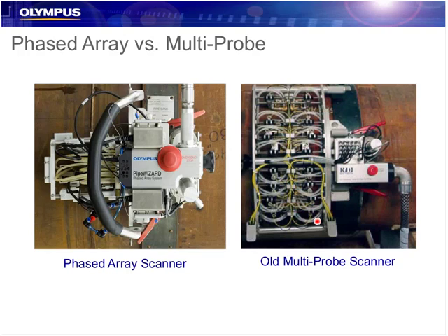We can imagine the trouble with this. Very precise. We have many, many different parts that can move. If one transducer becomes misaligned or if the scanner's dropped, we're basically not getting the full coverage of it. So now with phased array, we're able to replicate all those beams, actually get even more coverage than we could from 30 UT probes, and the mechanic is highly reduced. So holding the position of 2 phased array probes is much more reliable than the systems that we used to use using multi-probes.